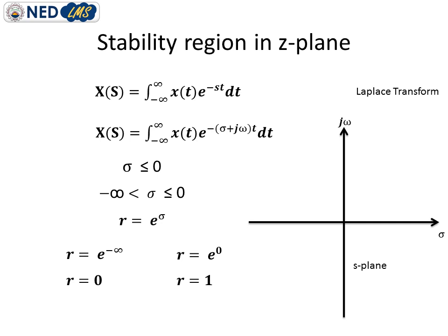As long as poles lie under this region, which is the radius of the circle from 0 to 1, which is a unit circle, it is basically the region of Z plane in which this system is a stable system. After the radius of 1 unit, the system will become unstable. So the range of the stability region in Z plane is a circle of unit radius.